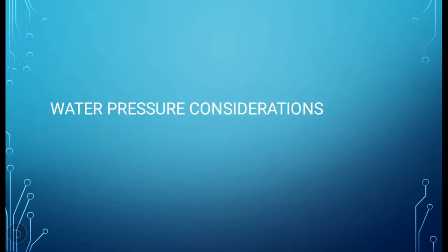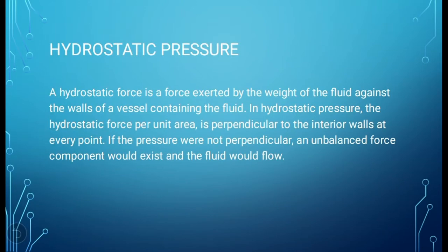For continuation, let's now talk about water pressure considerations. Hydrostatic pressure. A fluid, it's either in a gas or liquid state, molecules tend to seek equilibrium or stability of forces. When forces acting on a fluid are unequal, molecules in the fluid move in the direction of the resultant forces. Therefore, an elementary property of any fluid at rest or not flowing is that the force exerted on any molecule within the fluid is the same in all directions.